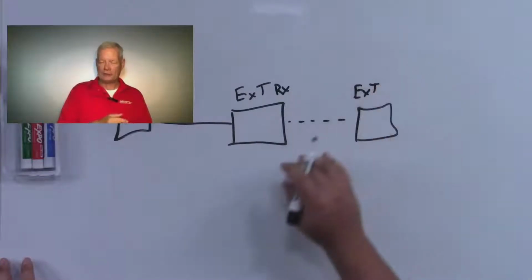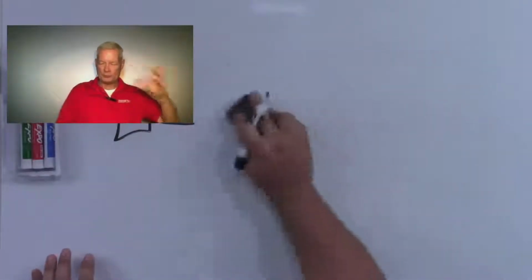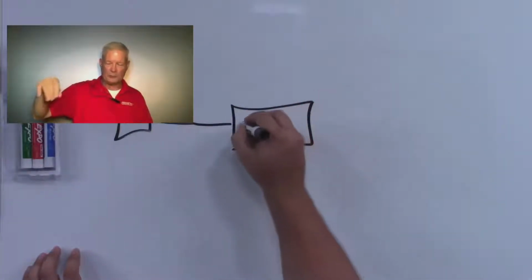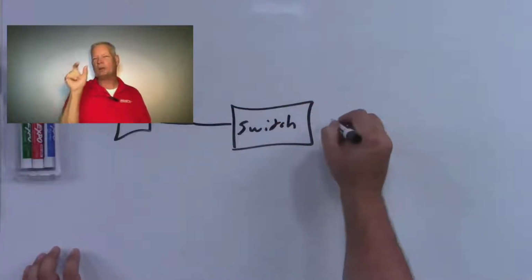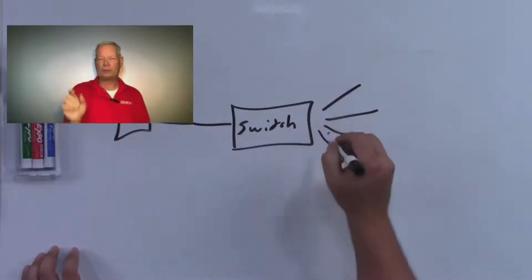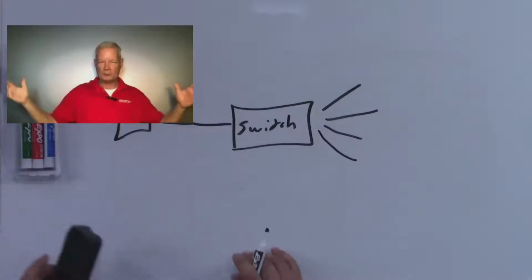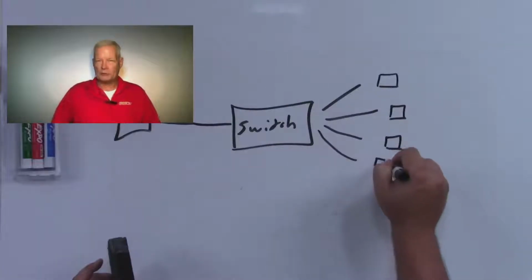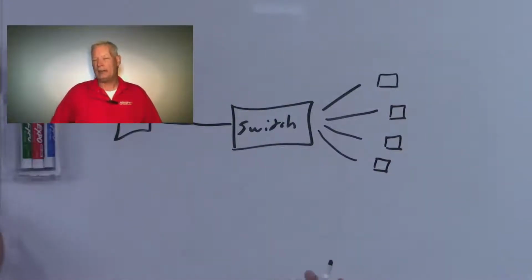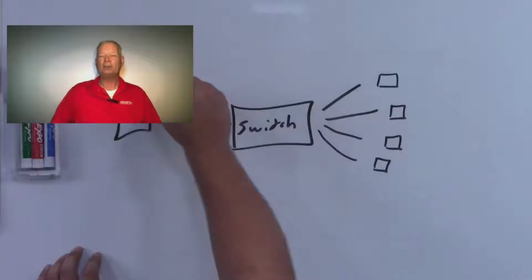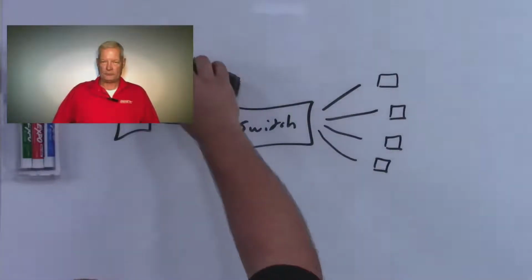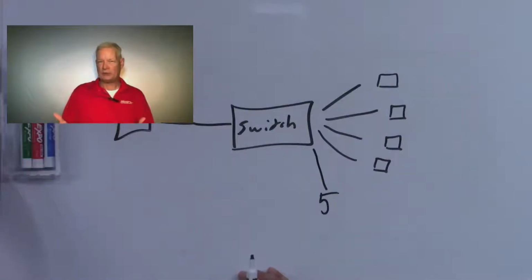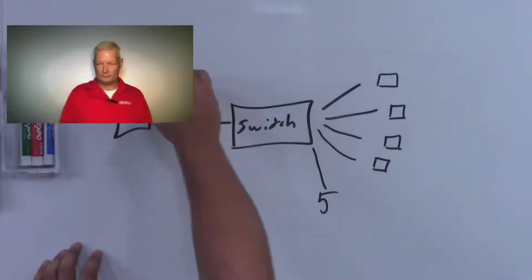We took a call yesterday. There were multiple sources going into the switch. Then the switch went through a 6-meter cable through a wall and then into a coupler behind the television, because they put the TV on a full motion mount, into another shorter cable. And the 4K source would only work on input 5 on the 5-in, 1-out switch. Would not work on any of the other inputs. I had him change the input on the TV, and then it didn't work at all.